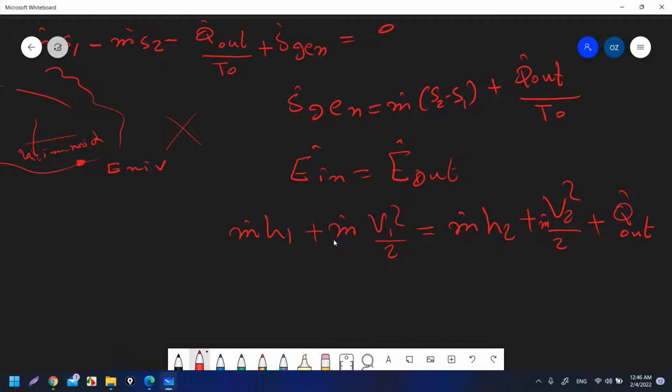Also the enthalpies. I have to get the enthalpies, H1, H2. Okay, that is it. So if I get these properties, I can calculate Q dot out, and then I can calculate X destroyed. Q dot out will be equal to m dot times (H1 minus H2 plus (V1 squared minus V2 squared) over 2), and we will divide by 1000 when we want to substitute, inshallah.